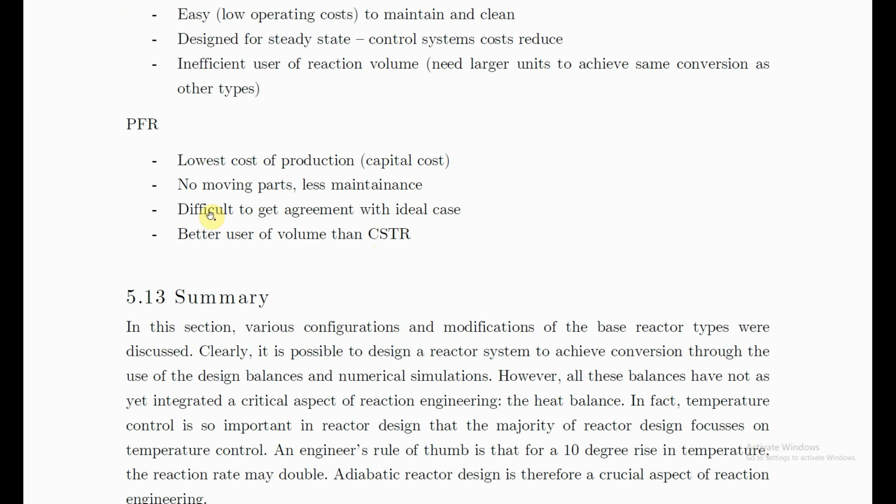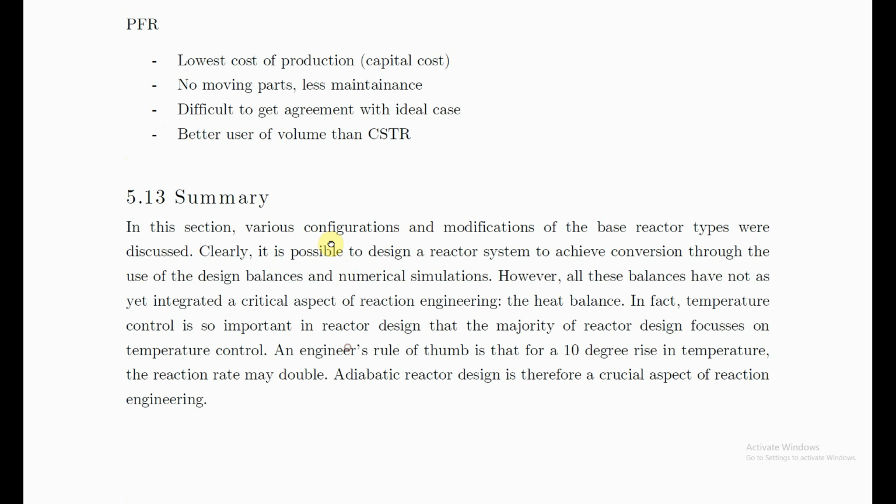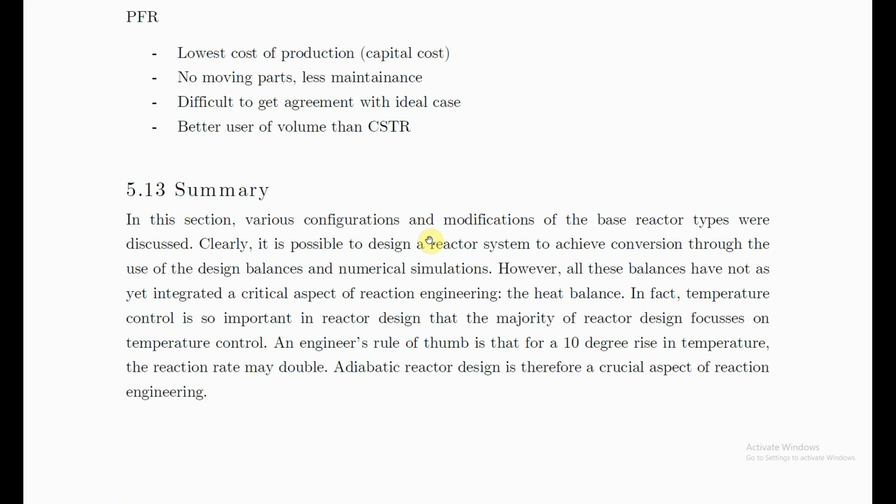But it's hard to develop a model for the PFR, because quite often laminar flow will still play its role, diffusion will still play its role. So these reactors can be a bit harder to predict in terms of their actual delivery of product purity and so on. Okay, so among those three reactors, yes, we know how their volumes behave, what types of volumes are achievable in each case. We also know how to design around those to improve the types of capital costs that we'll get.